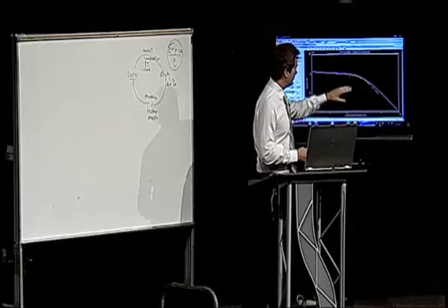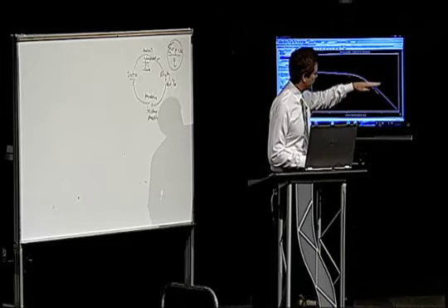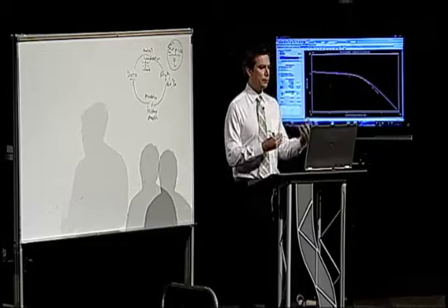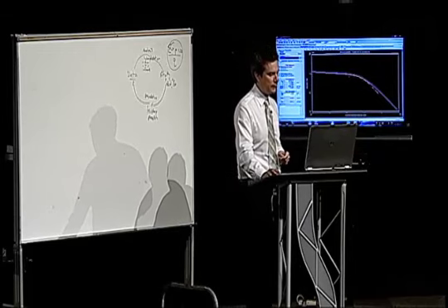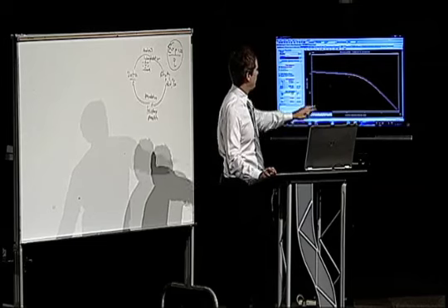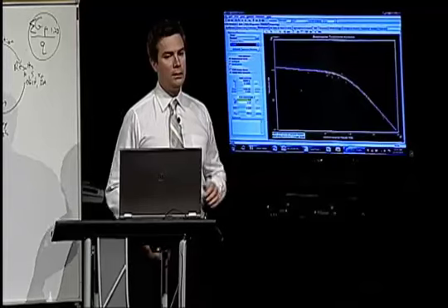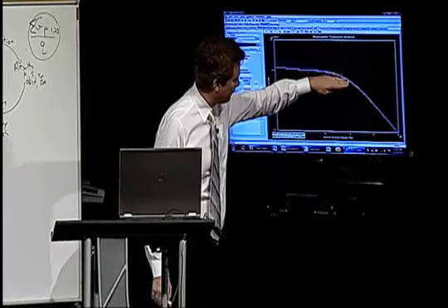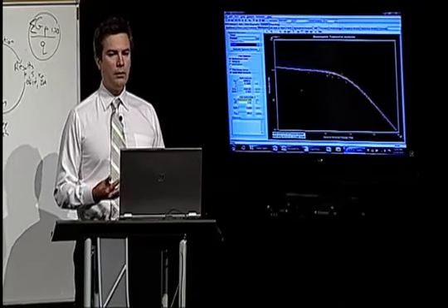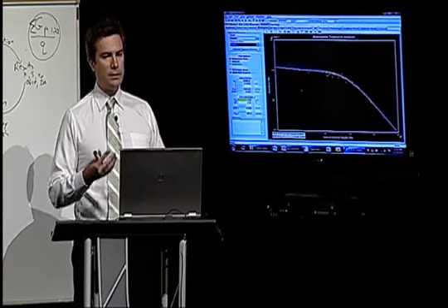By doing that, you can imagine all those data points are going to be shifted over because the cumulative volumes are higher for the grouping than they are for the single well. And the thought is that if I've included the proper combination of wells in that grouping, then I should get all the data to fall properly onto that curve. If I haven't included all the wells for the grouping, then it's not going to work.